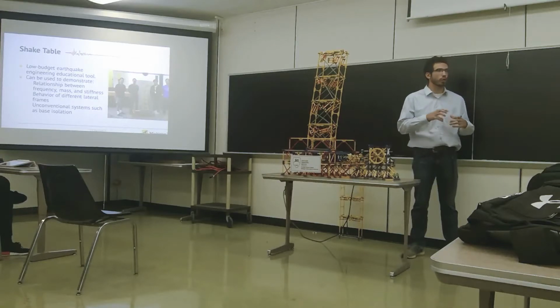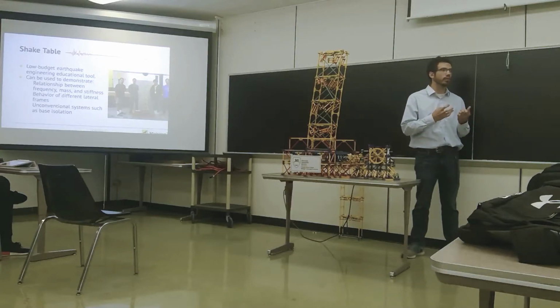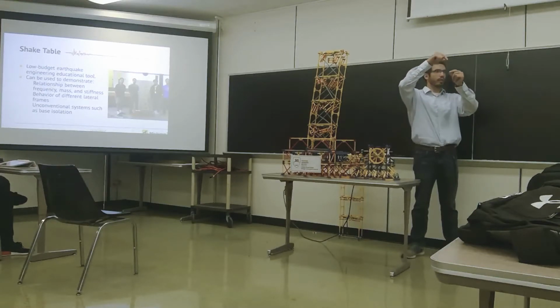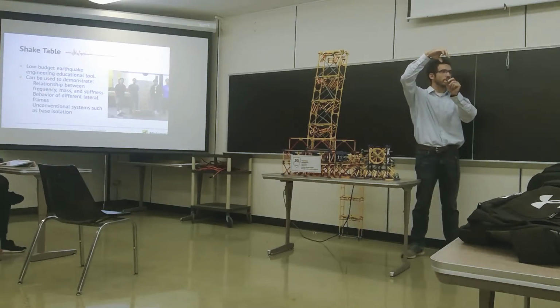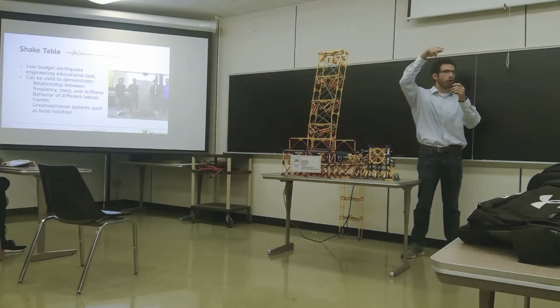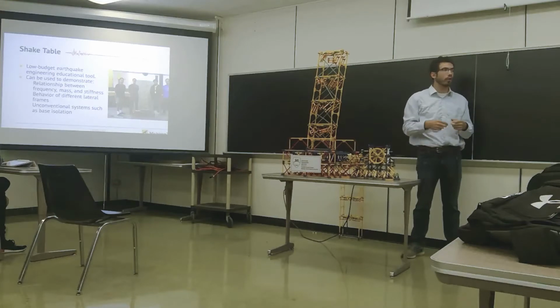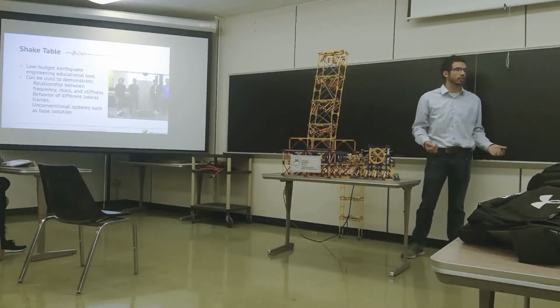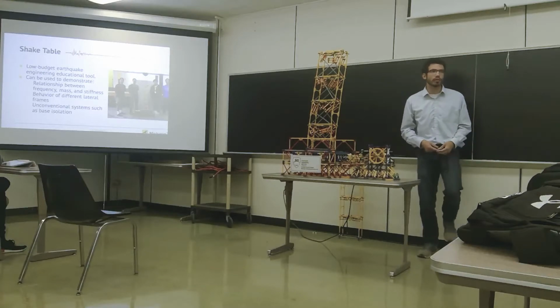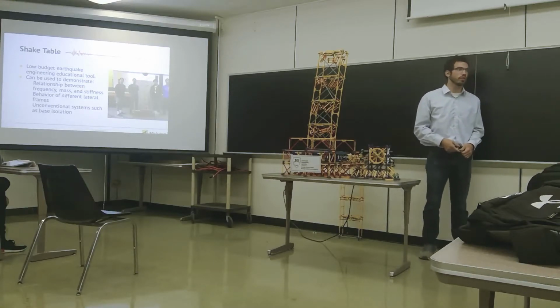So if there was a joint that was supposed to rotate and then got rusted out and locked up, which is common, for example, if you drive along highways and you see those bridges where they have a pin and hanger on some of the beams. On an overpass, the beams hang off this pin. Those are known to seize up, and that causes stiffness problems where the stiffness increases in the system. But generally speaking, if something is damaged, the stiffness will decrease.